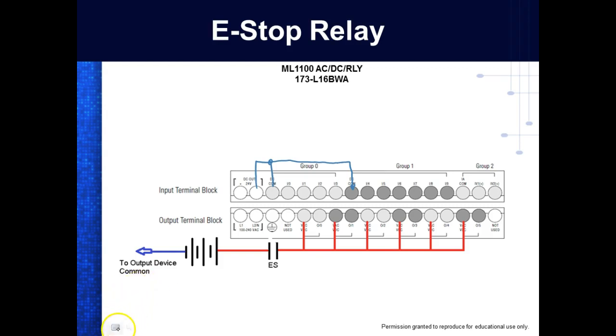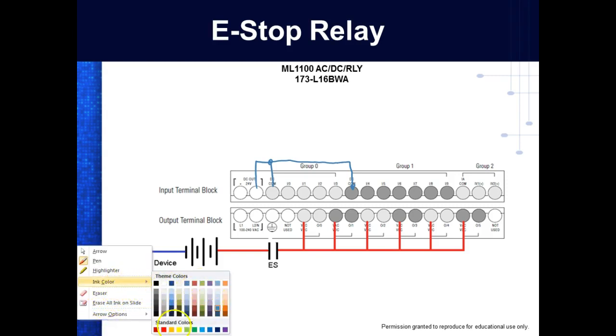And then what would we do? So syncing inputs means that your input devices have to be what? If your inputs are syncing, what does your actual devices you hook up to have to be? Sourcing. So what I would do is I would come up here and I'll do it in red.